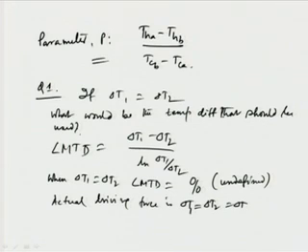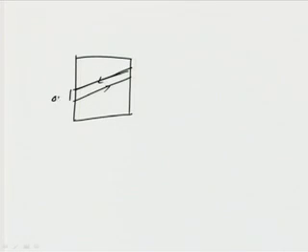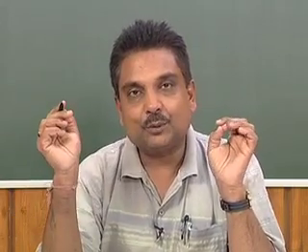And the second point is that in the case of heat exchangers, if we have an exactly linear driving force, say this is delta T1 and this is delta T2, and it varies linearly, there are no nonlinear variations, then our driving force delta T will be equal to (delta T1 plus delta T2) by 2. That is all. A simple arithmetic mean we should use when there is a linear variation of the driving force. We should use the same driving force when delta T is the same on both sides, and then the arithmetic mean will also do. And when there is a non-linear variation, then we should make use of the LMTD or log mean temperature difference.